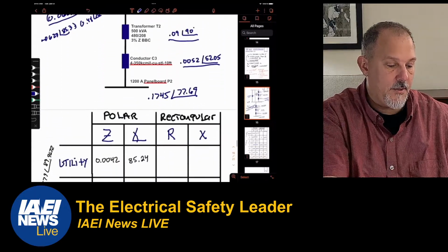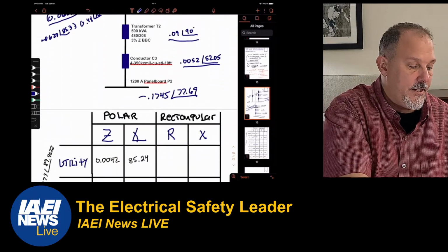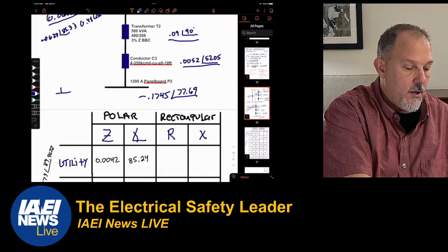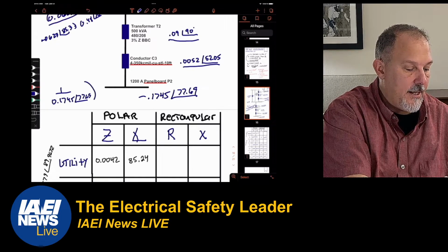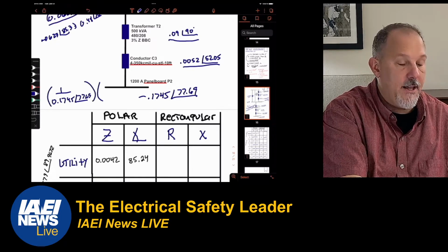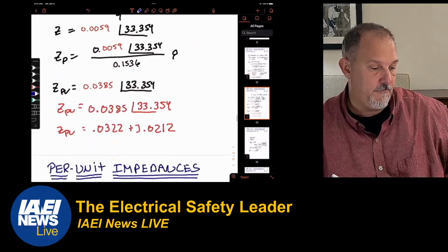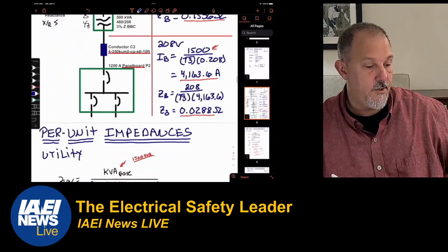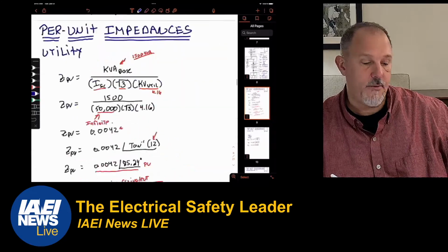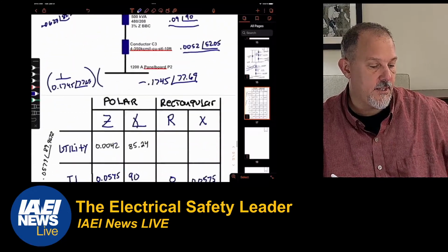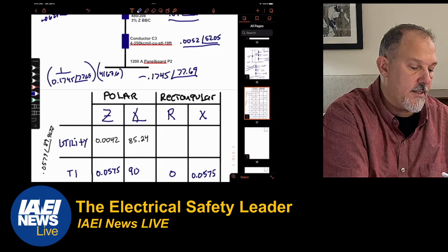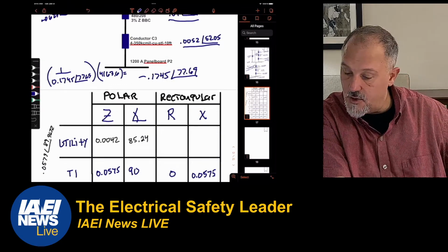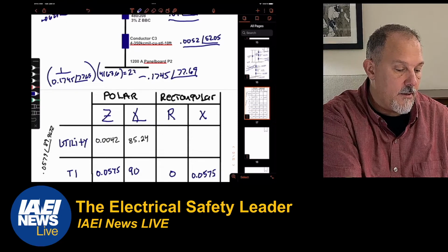So what I just did was 1 over 0.1745 at an angle of 77.69, and I multiplied that by the base amps, which was, I know I'm going to get you dizzy, 4163.6, and that came out to be 23.9 kiloamps.